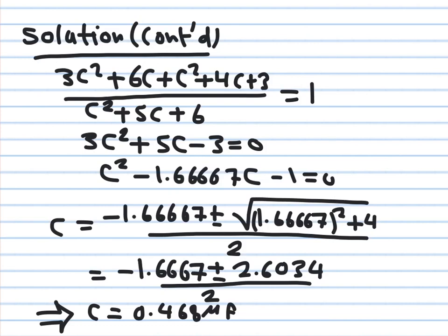microfarad for this combination. The conclusion of this example is, if you connect the capacitors in series, you treat them like resistors in parallel. If you connect the capacitors in parallel, you treat them like resistors in series.